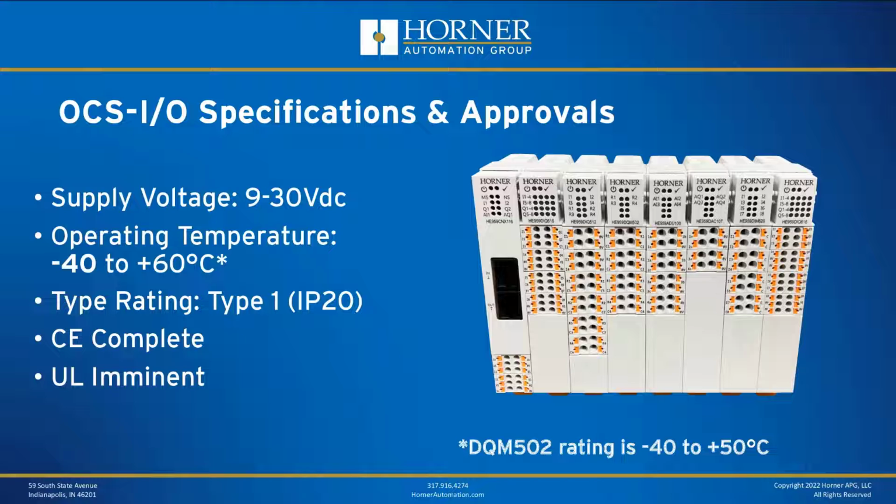Now, I have also previously mentioned that the high current relay output module is limited to 50C instead of 60C. Environmentally, it's designed to go inside of a control enclosure, so it's only IP20 rated or NEMA Type 1.